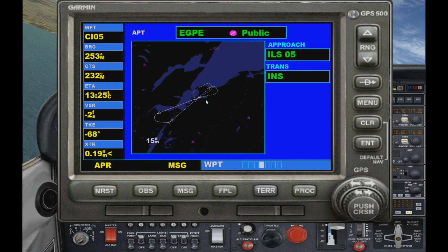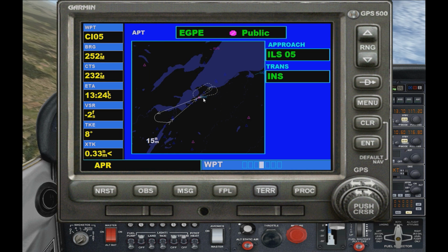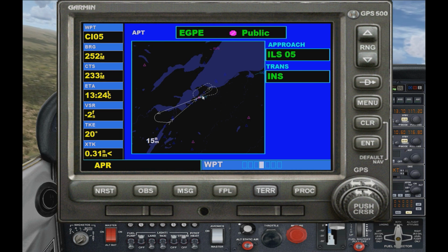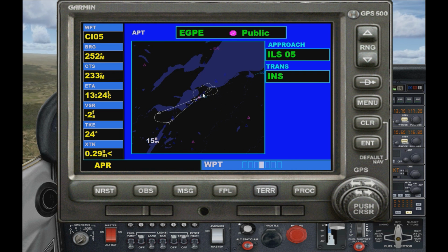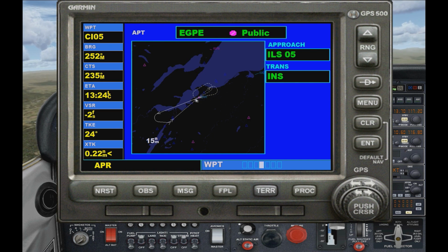For example, if we have a look at the ILS-INS transition again, you can see we've got the solid line here, which is the actual approach, with the arrows designating the direction of flight, and then you can see the dotted line is our missed approach. So while we're flying away, I'll take a second to explain that. So the missed approach for Inverness, if we miss the runway for any reason, be it bad weather, high winds, or an obstruction on the runway, what we would do is we fly the runway heading, and then we loop back towards the Inverness VOR, and then we simply enter a holding pattern above the airport until we decide what to do.